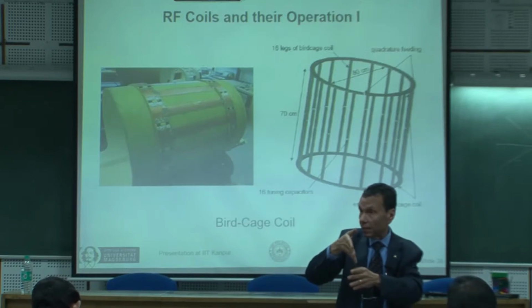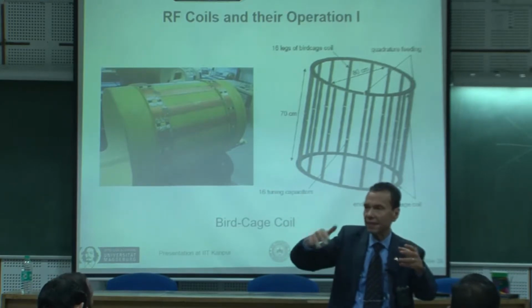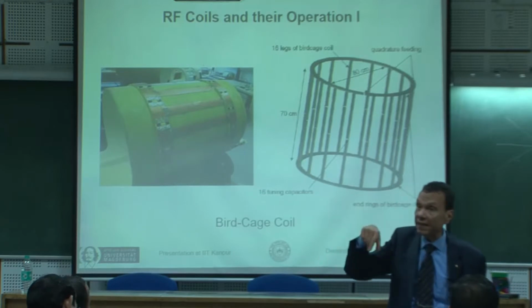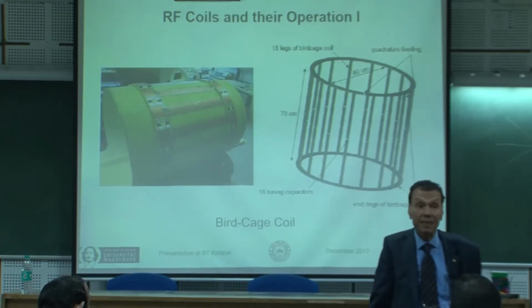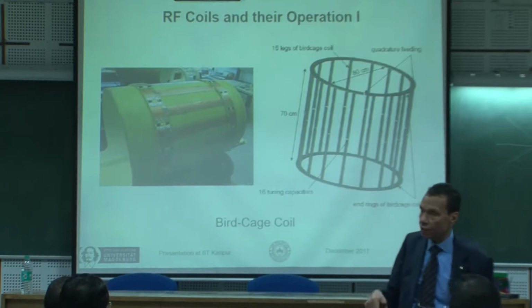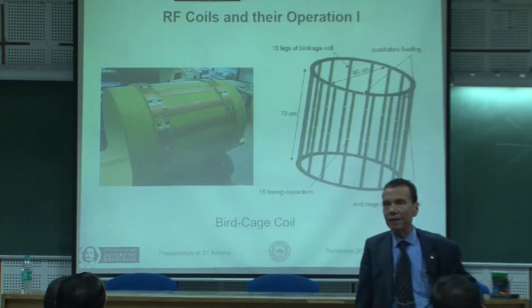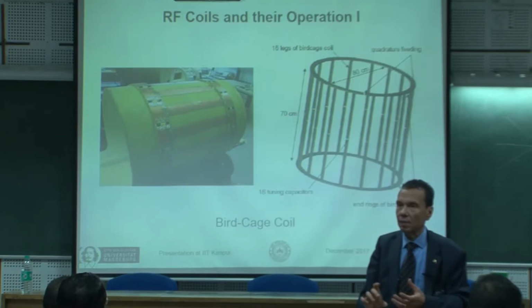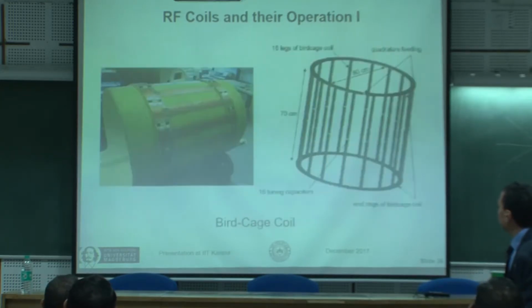in the current, and if you do some analysis, you can see that it is something like cutting and keeping the current constant. So you insert capacitors, and the number of capacitors, whether along the rods or in the ring, depends on which tolerances you have. The capacitors must be high quality capacitors, because each source of losses will degrade the quality factor. So as a whole, you will have a combination of short rods separated by capacitors. The whole thing is a periodic structure. This is what is called the birdcage coil or whole body coil.